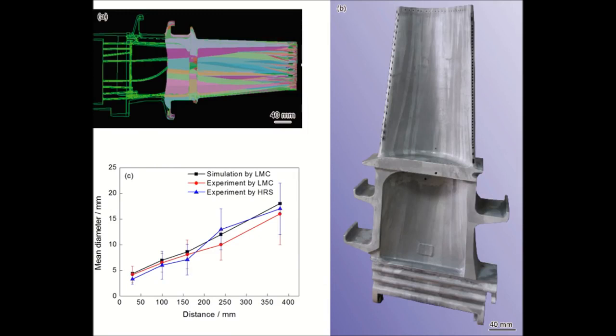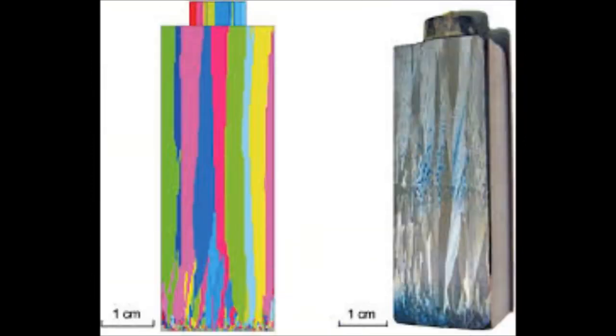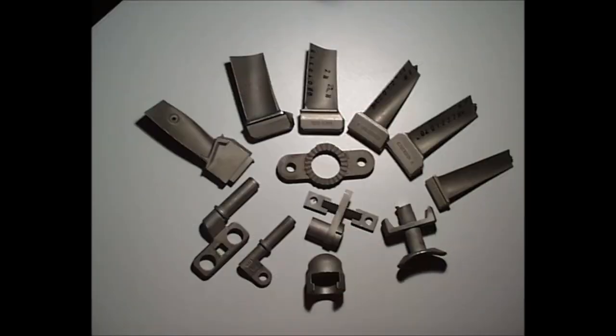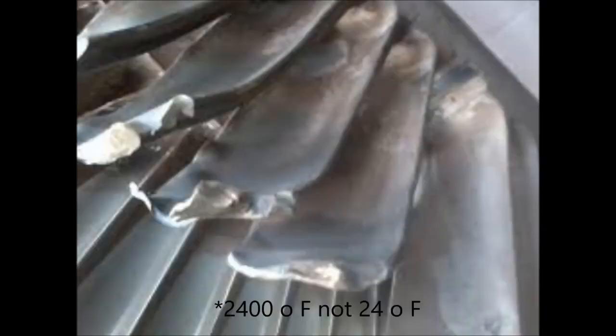DS arranges the crystals in layers, eliminating some of the grain boundaries in the tensile direction, or the vertical direction, but not in the horizontal direction, improving the thermal fatigue, but not to the extent needed. However, SC took it one step further. This process allows for a casting of a blade with one single crystal. One single superalloy crystal completely eliminates grain boundaries and allows for a material with the capability to withstand a great amount of stress for much less strain than ever before.